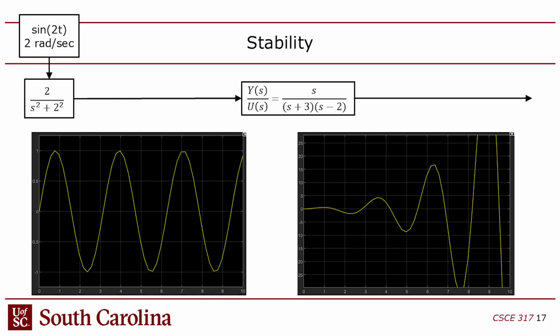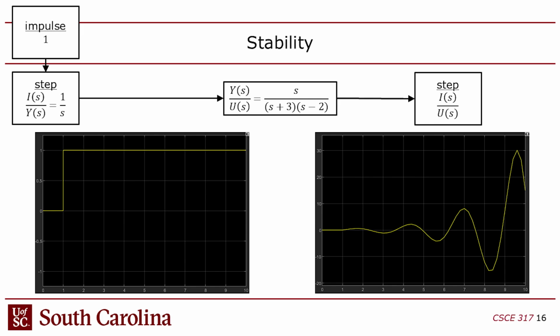Now you might say, why in the world would we do that if you can just look at the denominator of the transfer function and find the roots of it, right? Well, yeah, but that would only work if you had the transfer function. Sometimes you don't have the transfer function, you've got a black box and you just hit it with the step. If you don't know the transfer function and you want to know if it's stable, you hit it with the step function or an impulse. If you have the transfer function, then it's probably best to just find what values of S will give you a zero denominator, right? The poles. Make sense?